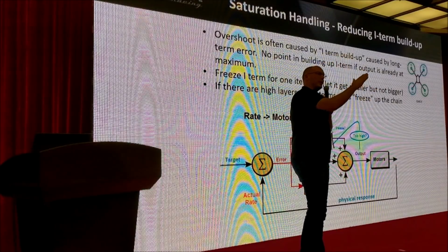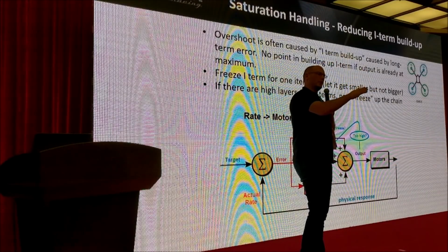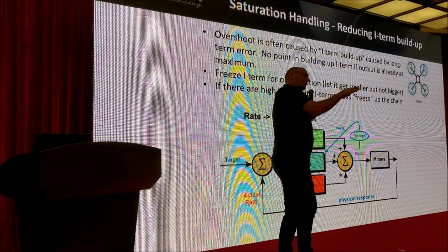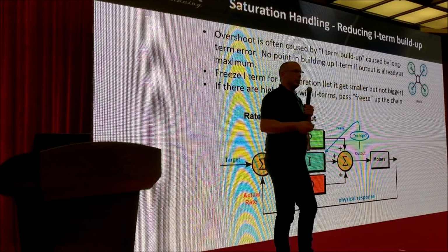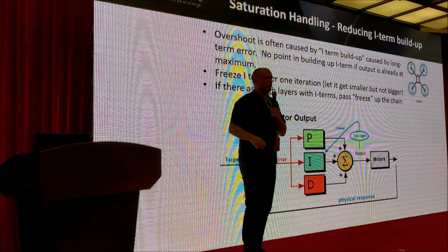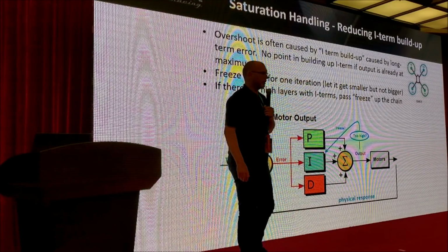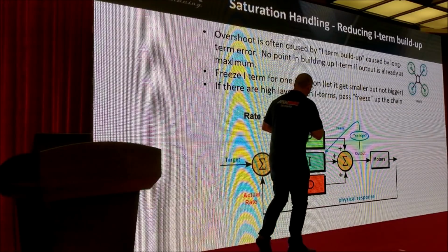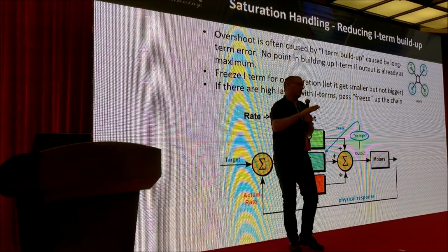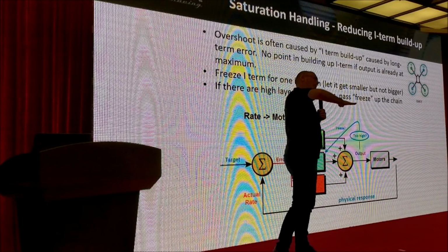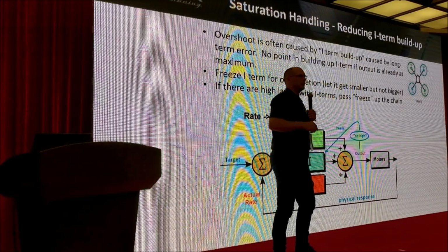On the ground, if we're at a slope, the PID controllers are trying to level us and make us level. But because we're on the ground and the motors are all the way down, we can't do that. So the I-term is constantly getting bigger and bigger and bigger to try and lift that aircraft up and make that error 0.